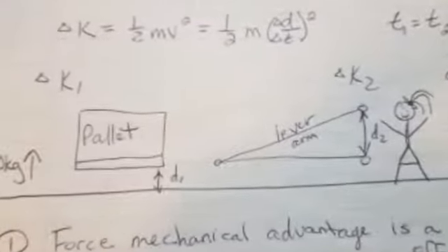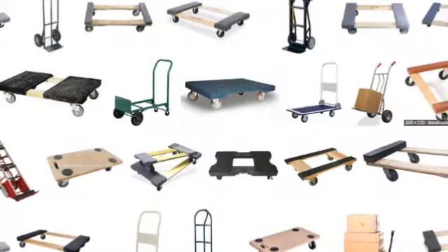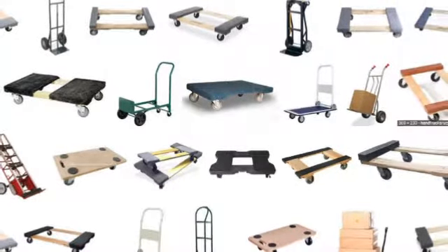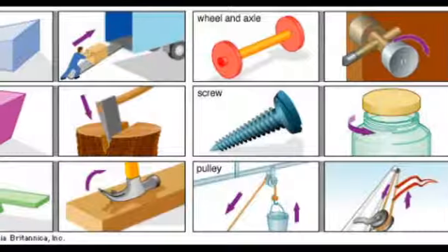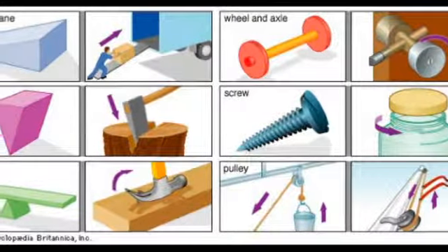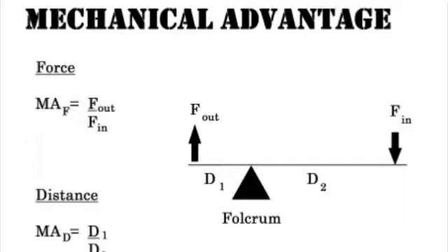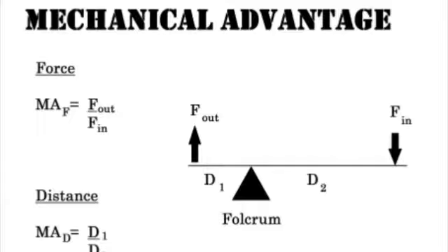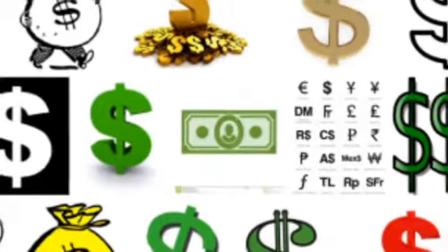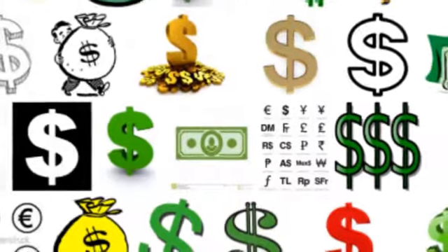Now, let's picture the same box on wheels. It would take less force to make the same movement, right? The wheels provide mechanical advantage to the system. Mechanical advantage is gained when a simple machine, like the wheel, is used to reduce the force needed for the intended result to still occur. It ultimately is a ratio of input force to output force. Moving everything by hand without mechanical advantage would have taken forever and cost the theater thousands more in labor costs.